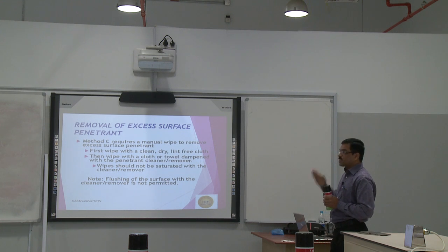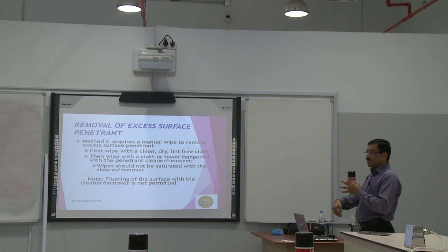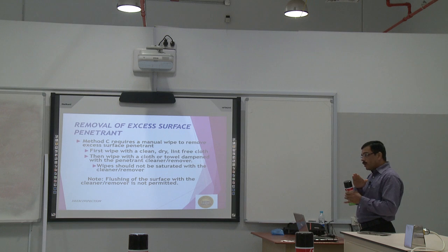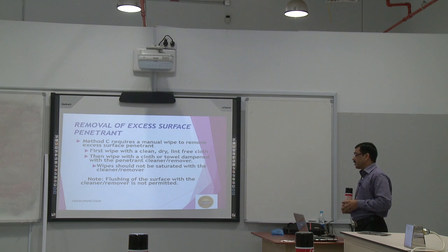So the surface should be properly cleaned. That means the excess penetrant. We are not touching whatever penetrant has gone into the defects. Only the surface penetrant we clean, until the final trace is gone. That is the cleaning method, the removal of the excess surface penetrant.